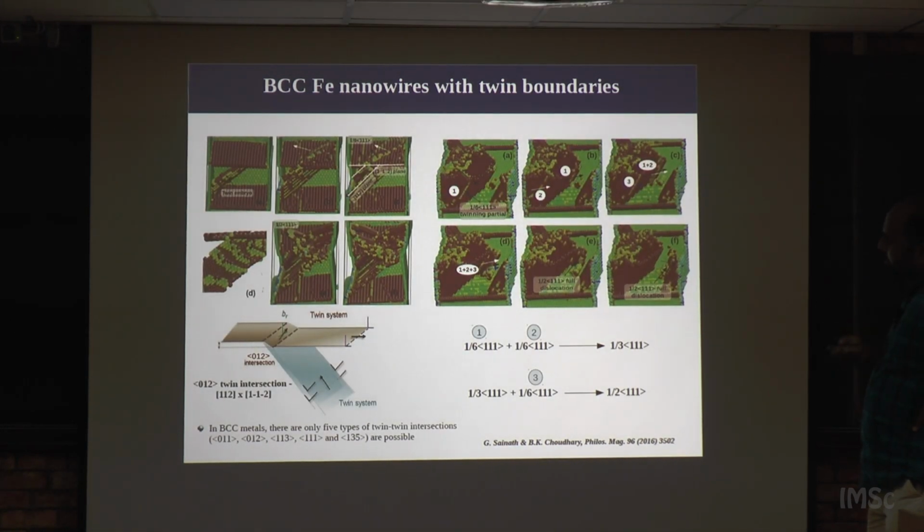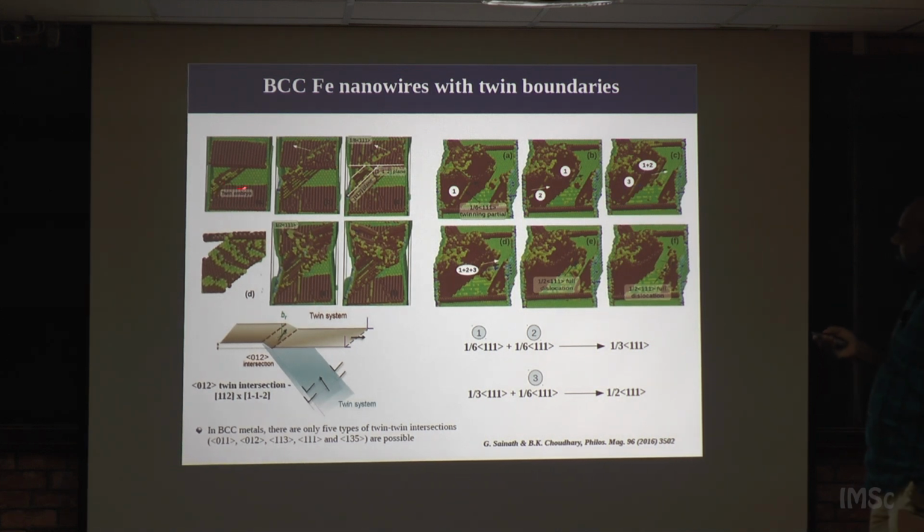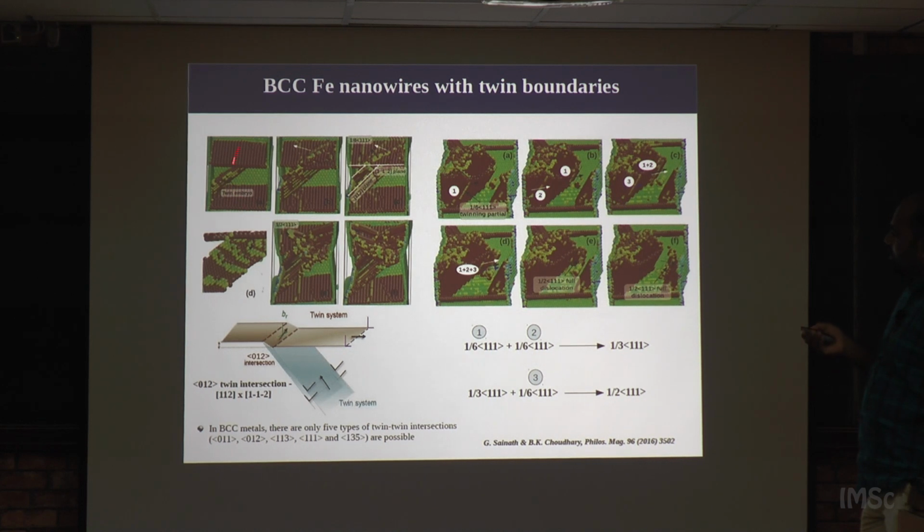So, this is how dislocations or twins transmit through the grain boundary. As you can see, the twin is here, so how does it grow to the next grain? This is one twin boundary, and this is the twinning mechanism that is coming from the deformation. As you can see, it comes and interacts at this point, and it leads to partials which are transmitting along the grain boundaries. It does not just go to the next grain, but the dislocations move along this twin boundary plane. Okay. And also there is an accumulation of dislocations, basically the partials, at the downside of this twin boundary, as you can see here, and at larger strains, those dislocations also transmit to the next grain.